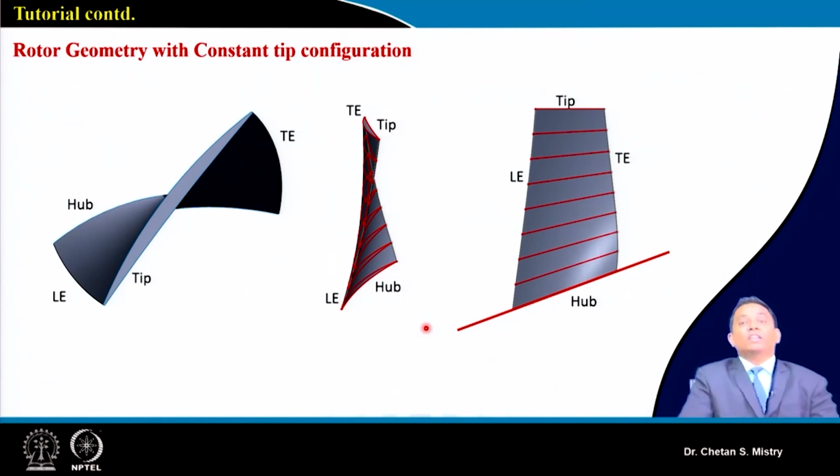Now here, as we have discussed, because of the change of my density and the change of my pressure ratio, my exit dimension will be different. So under that condition, my aerofoil at the hub station is not a 2D aerofoil. Suppose if I say 2D aerofoil, I'll be having my hub radius the same. Now based on my inclination, I need to modify. So this aerofoil is no more a 2D aerofoil, this is a 3D aerofoil.